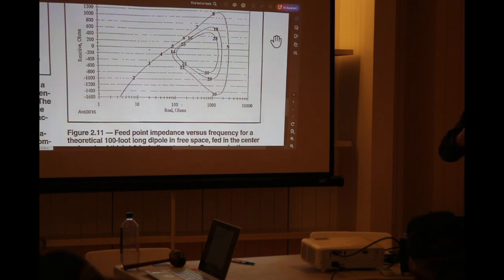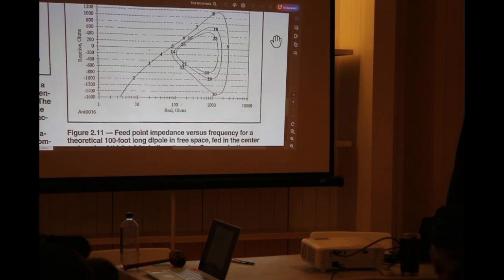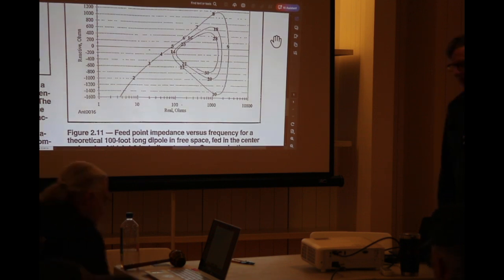And now what we do is take the VNA, measure the impedance at one side, and then we short it out and measure it again. Now we multiply those together, take the square root, and that's our characteristic impedance. So, any unknown length of transmission line, we can find its characteristic impedance. Pretty cool. But it only works at a quarter wavelength, and it can only be a quarter wavelength at one frequency.